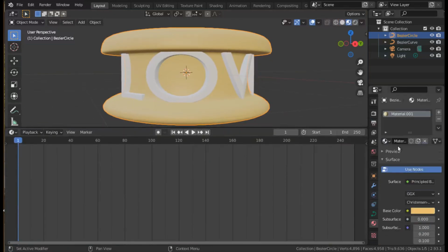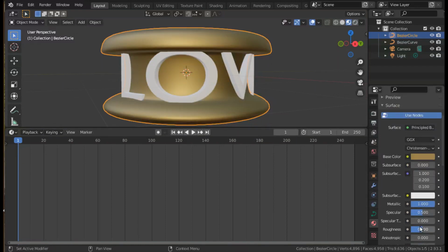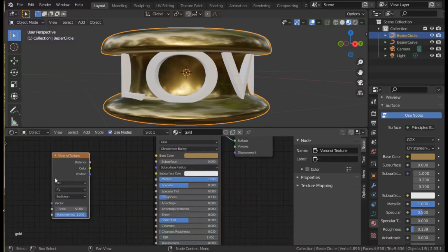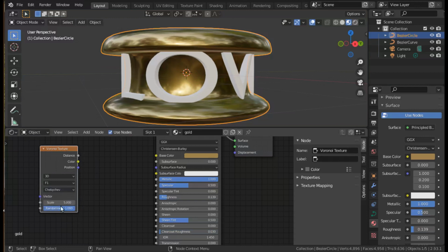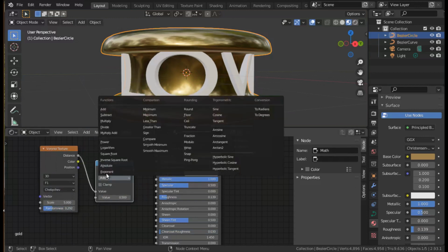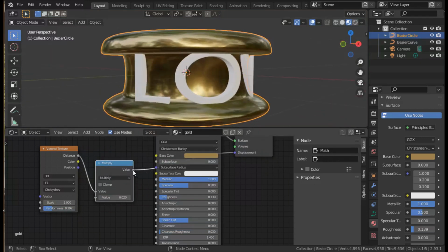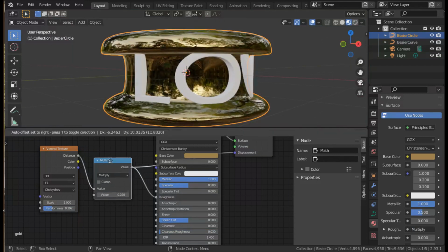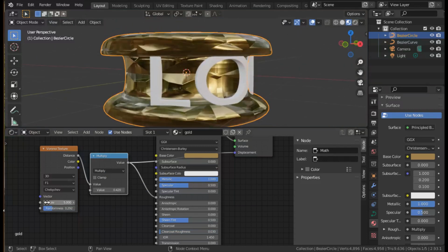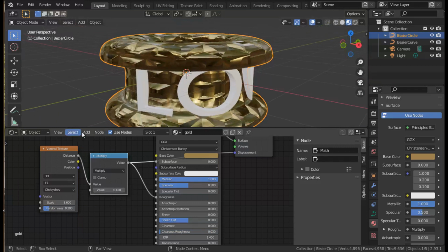So we parent the text mesh to the curve, and then we set the materials, just as we did in chapter 1, set the material to a suitable gold material. This time I'm making a Voronoi texture using the Chebyshev algorithm, which produces a more rectangular pattern, especially with low randomness, setting the displacement and the roughness. Anyway, it's just a variation. Once we've made the material, we have to also assign the same material to the lettering mesh object.